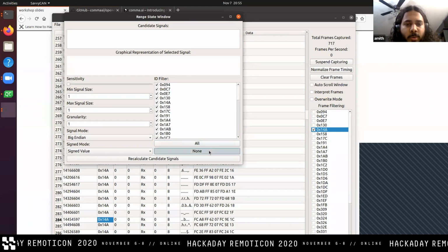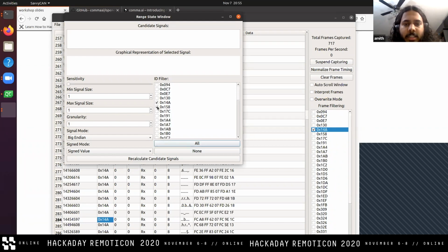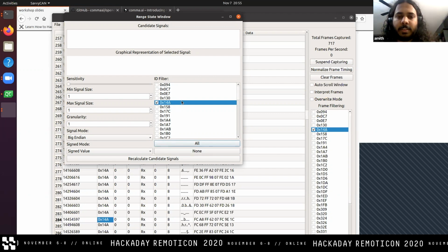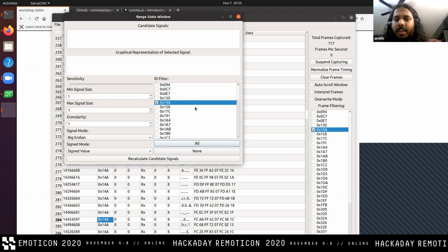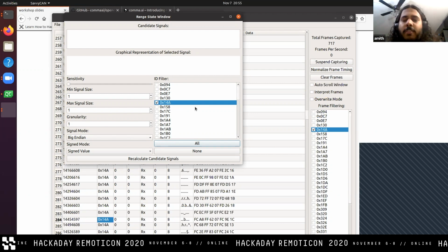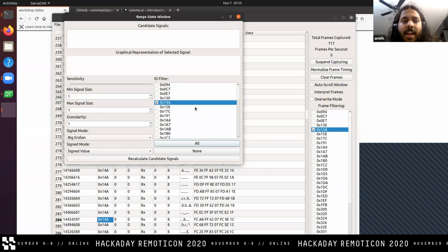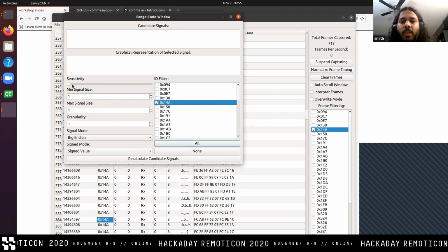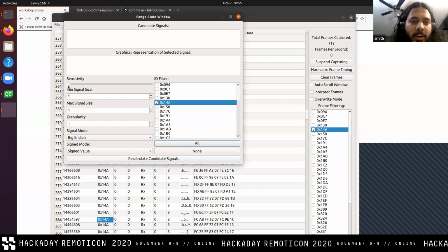Okay, so this is a pretty cool tool. I'm just gonna select 14 and just another, and we're gonna figure out, so let's say I ran the Python analysis and I found out 14A is our CAN ID that's valuable to us for whatever reason. So, we want to parse, figure out what kind of signals are stored within that message.